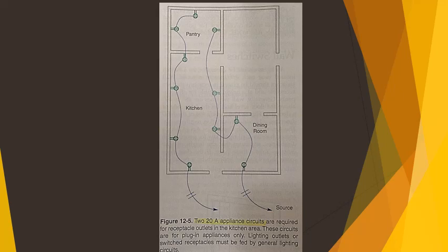See figure 12-5. Also required is at least one 20 amp, 120 volt outlet in the laundry area. Refer to Article 220 of the NEC for specific rules on these circuits. Also review the tables and examples in Chapter 9 of the NEC.